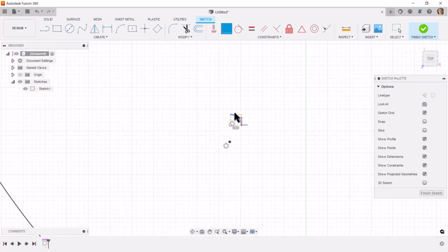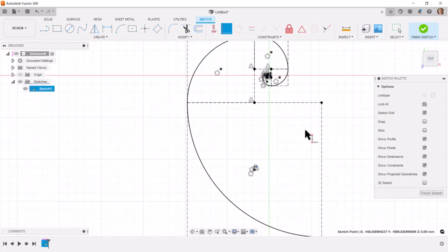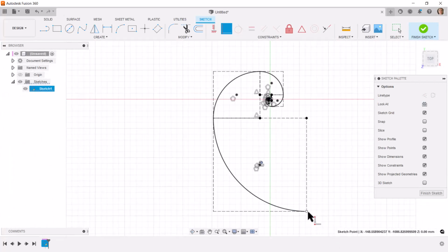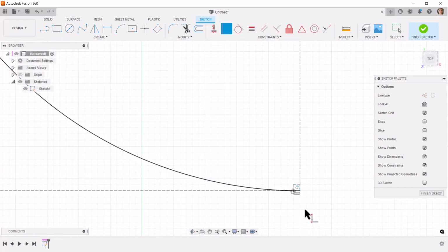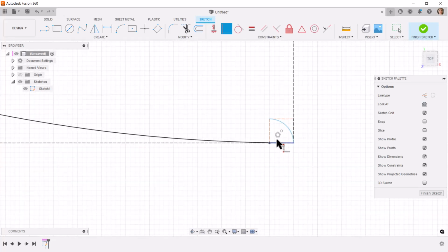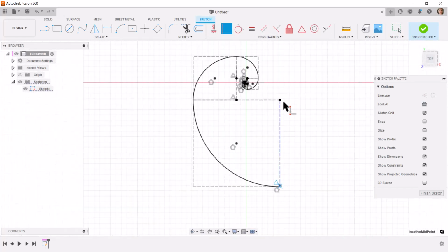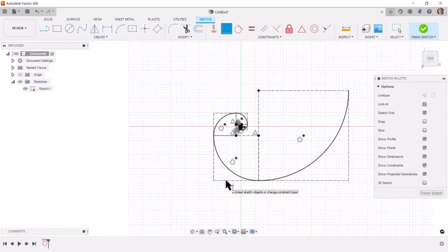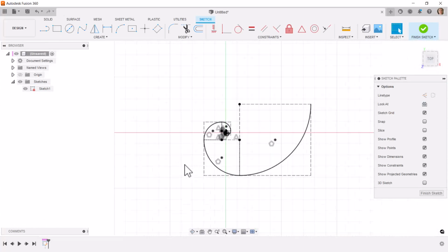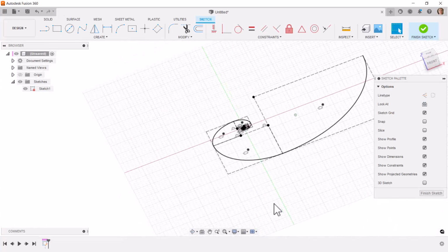I'll do this point to this point, and again, this one I copied with the constraint, so I need to remove that horizontal constraint. And now I'll put that in coincident, and I'll do shift here to here. Okay, so I've shown how to set this up.